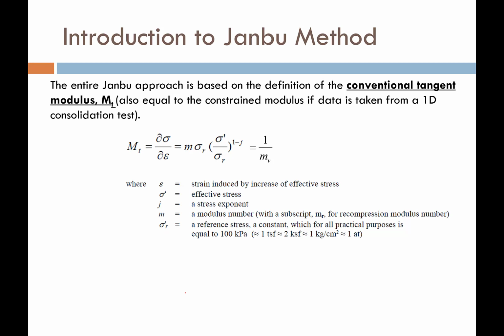So here's the fundamental approach. This tangent modulus approach is fundamentally based on this parameter M sub t, which is the tangent modulus. And the tangent modulus comes straight from the consolidation curve. It's just equal to the change in stress divided by the change in strain.